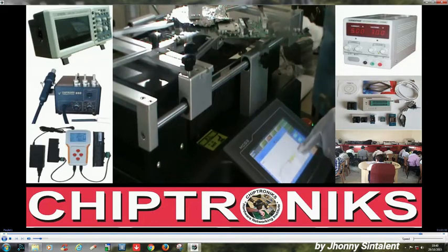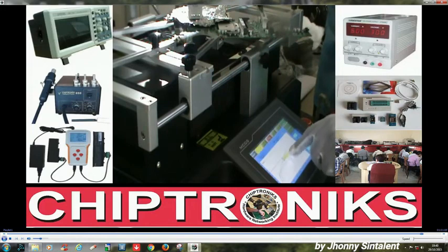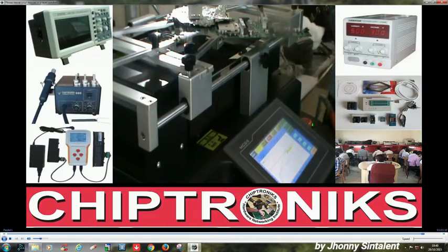See, the time is 168 seconds for the higher heaters. You can see over here, and if you touch over here, it will show you the temperature 238, and close here 258. You can see the temperature that is currently running on the BGA machine.